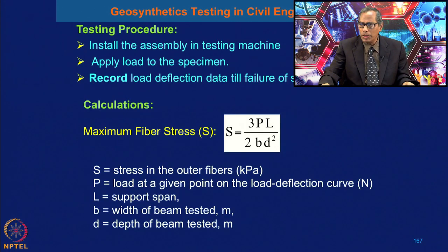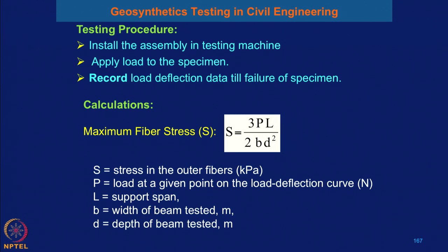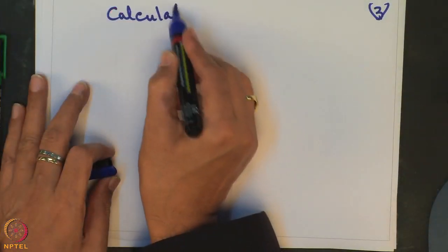Now, the testing procedure: install the assembly in the testing machine, apply the load to the specimen, and record the load deflection data till failure of the specimen. Then, how to calculate the flexural stress of the geofoam material? For the calculation for the EPS geofoam material, we are showing some calculations.